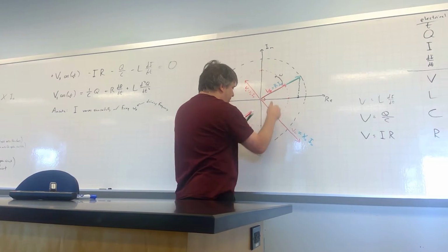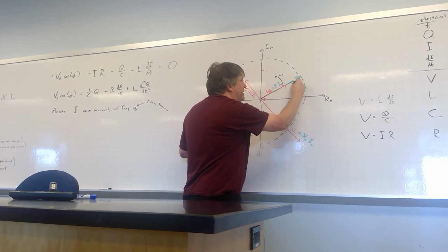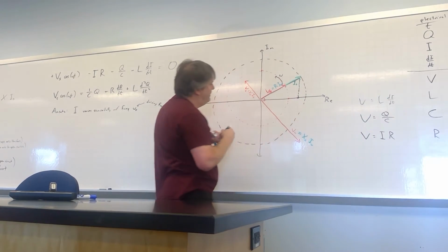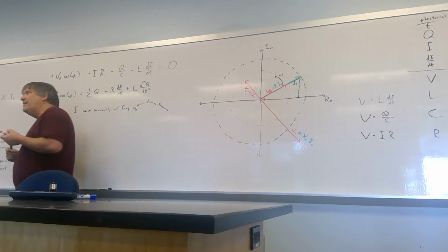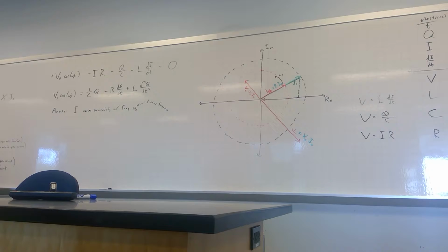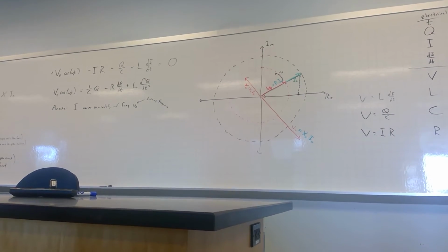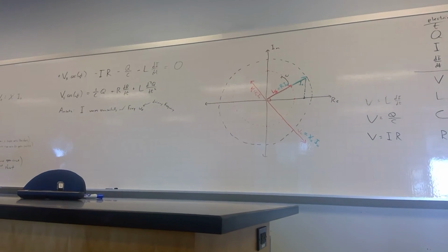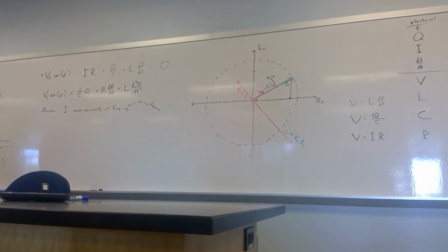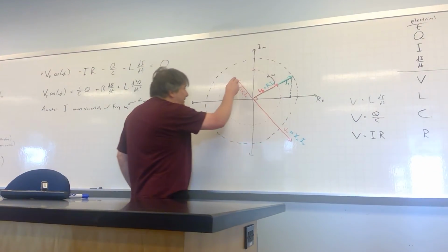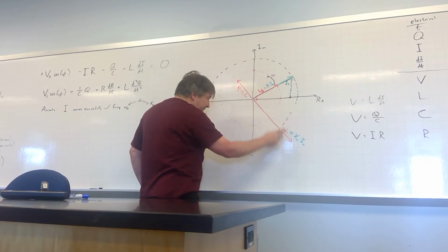Phasor. Go ahead and put that label out here so we know which phasor it's talking about. Okay. Now, at any given moment in time, I get the total voltage across those three devices by adding up those three red phasors. Now, of course, what we're actually physically measuring in real life is the real projection of